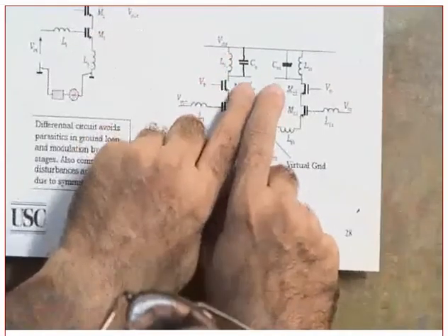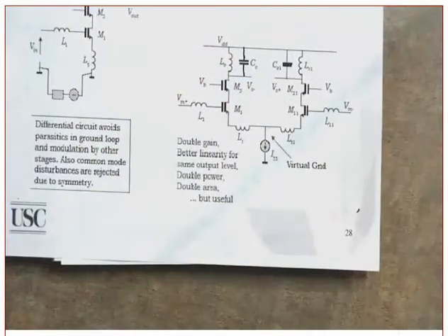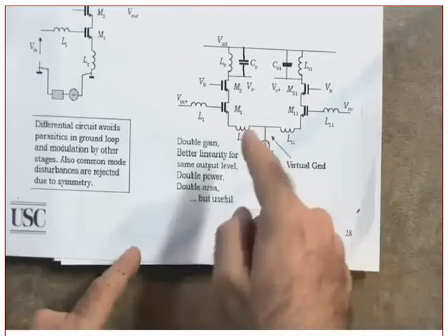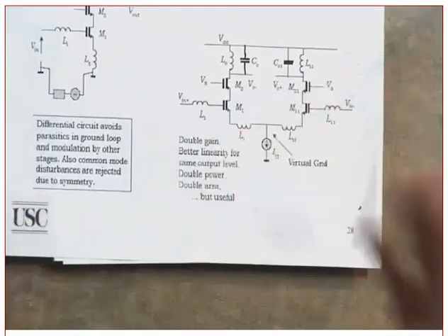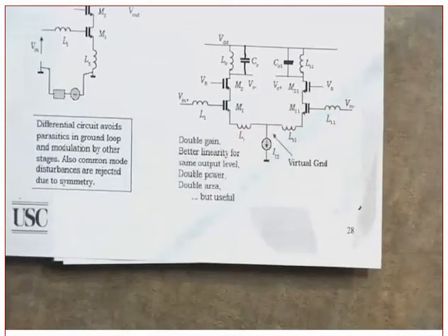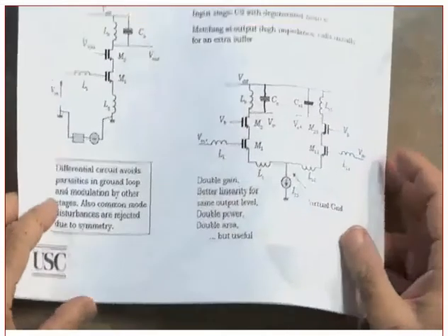Now, the voltage, when you take it from here, it's a what? It's a differential voltage. When we get to the mixer, we will see that most popular mixers do use differential local oscillator and differential RF. Yes? If we need differential RF in the mixer stage, what do I need to use? I need to use the LNA as a differential. Did you get this or not? Yes or no? But I will show you that when we get to the mixer. Right now, I'm not sure you are following me here.